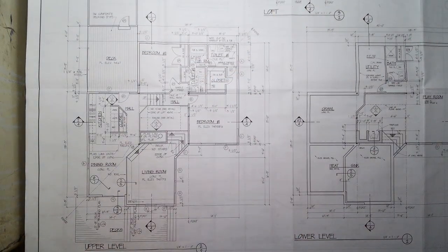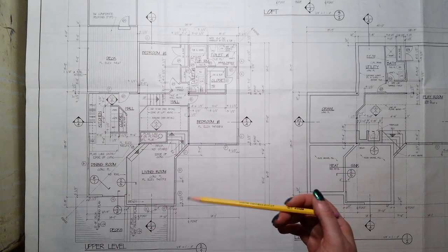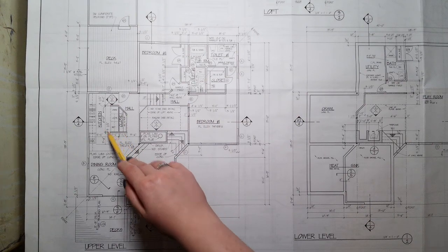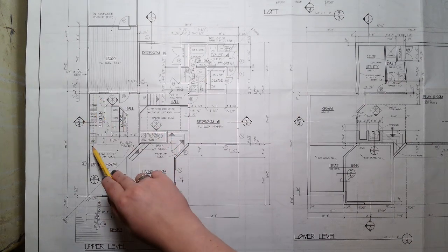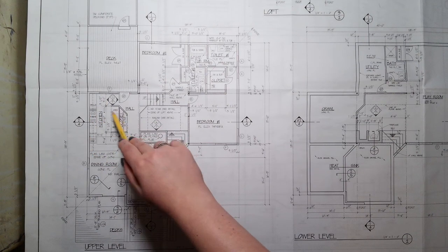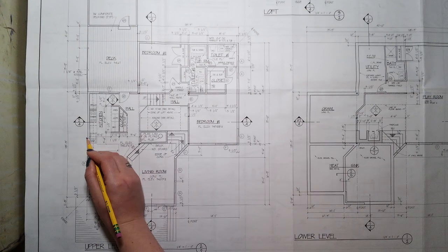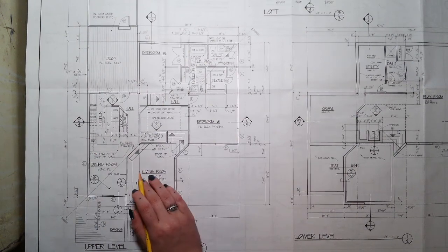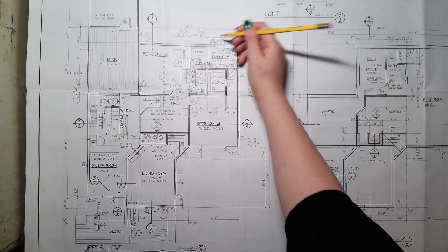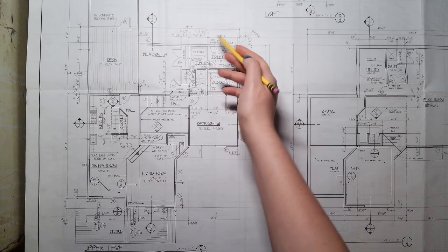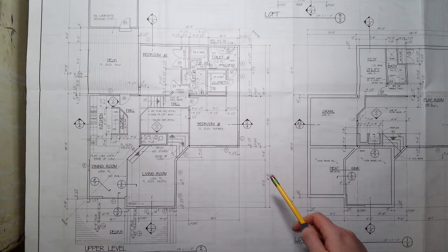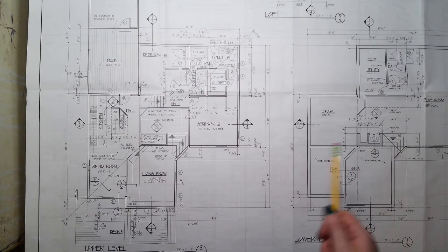You also want to think about walls that are going to have different pieces of plumbing inside of them, and how that's going to come into the layout. So for instance, we've got all of our kitchen stuff right here, which means that if my sink's here, I'm going to have plumbing running in through this wall. I'm going to have plumbing coming in through this one as well, and this one, and here, because if this is where my toilet and my shower and everything's going to go, I need to think about which walls are going to have the different pieces of plumbing going on in them.